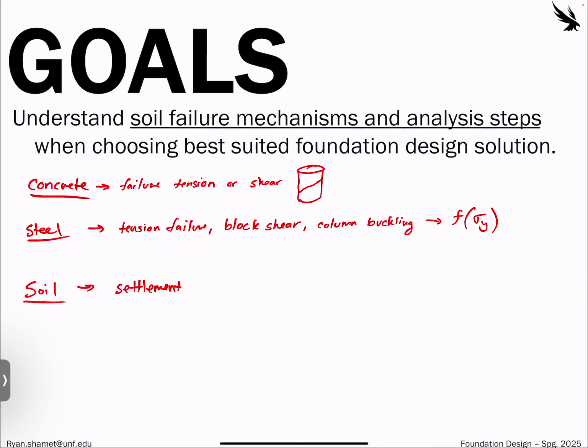The other thing with settlement that we'll see is that settlement is also time dependent. This is going to be something where we talk about clays and this fun word called consolidation, which we're going to touch on next week. It could all settle before people get in the building, before you connect all the utilities, and before all the people inhabit it. Or it might settle 30 or 20 years from now and really screw up everything in a slow process. So settlement is a function of time, which is another headache.